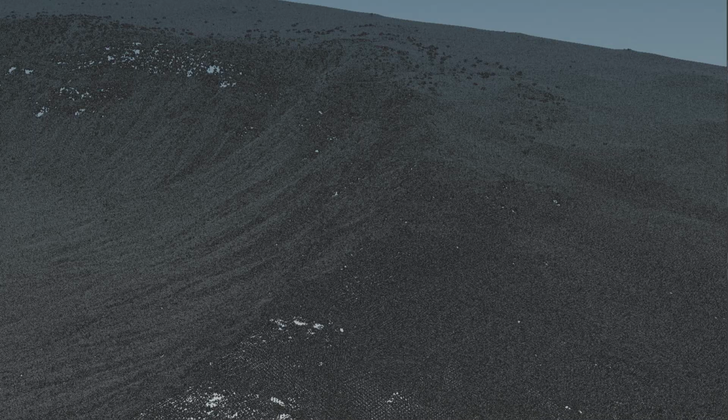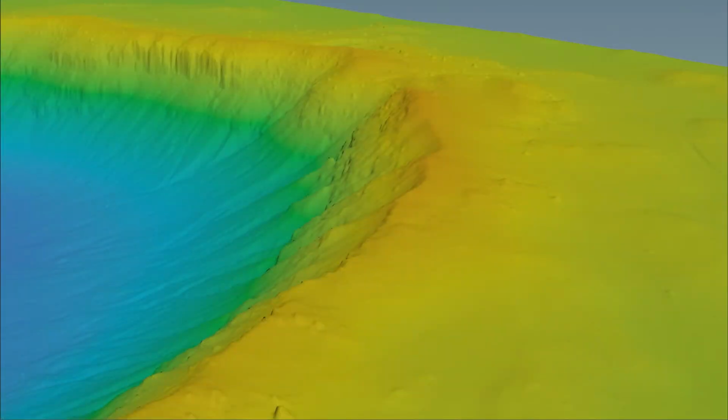When we look for datasets online, we try to find those that are at least 1 point per meter. Here we see one of the products that you can derive from Lidar, which is called a DEM, a digital elevation model. It's basically a grid of rows and columns that build up the surface. If you download the DEM product, it would be a GeoTIFF file that also contains metadata, like the Lidar points also have. I'll talk later about how we read those Lidar points in. It's with the Lidar import node in Houdini.